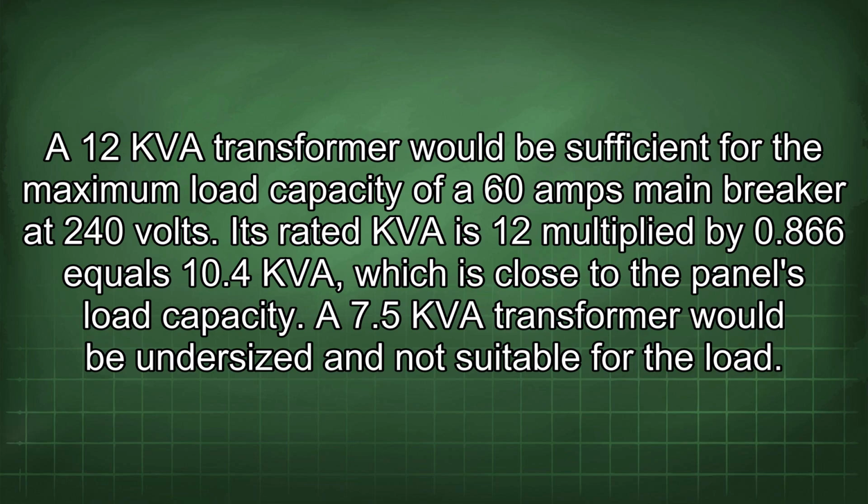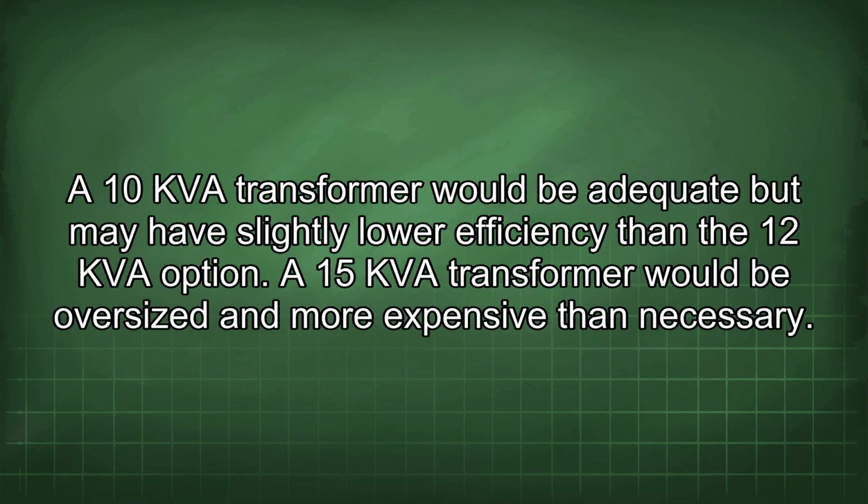A 7.5 kVA transformer would be undersized and not suitable for the load. A 10 kVA transformer would be adequate but may have slightly lower efficiency than the 12 kVA option. A 15 kVA transformer would be oversized and more expensive than necessary.